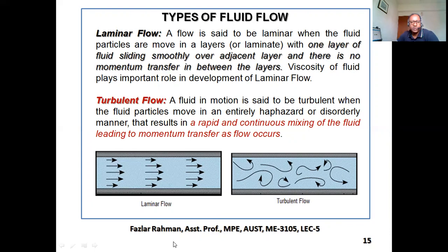So in laminar flow, the fluid particles flow in layers. The layer close to the wall will travel at a little lower velocity due to friction. The layer immediately above it will travel a little bit faster, because the bottom layer tries to hold it down.